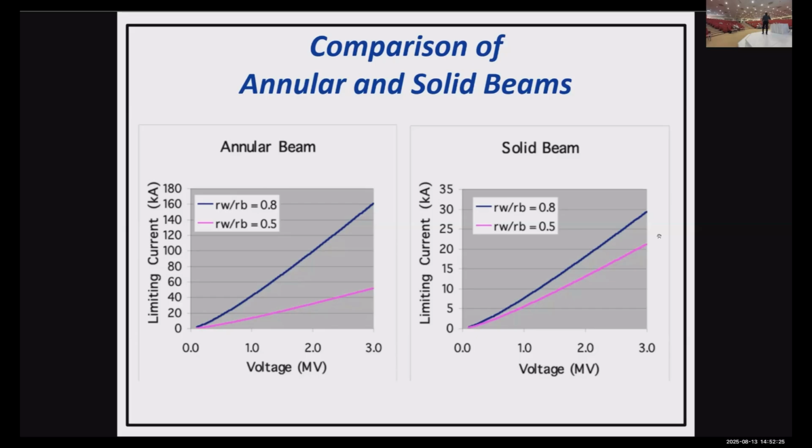It's very, very high current. You don't want to have any electrodes near it, because they're going to start arcing. It's really a challenging task. That's why we don't design the electron gun the way people do at lower currents, with electrodes at different voltages, of course. And also the pulse width contributes to this.